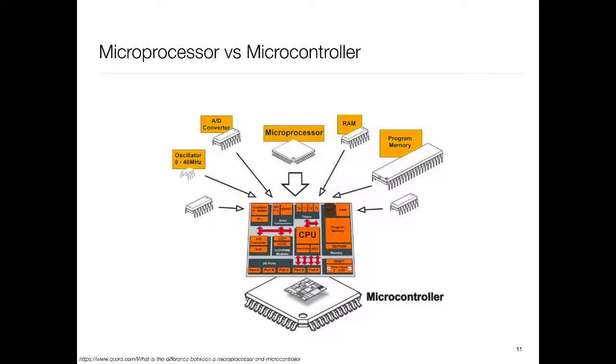Okay. So what happens with a microcontroller is that a lot of things which otherwise would be on the board are now on a single chip, but of course nowhere near the same size. So the amount of memory you would have is very little. In fact, most microcontrollers do not allow you to plug in external memory. If you look at a microprocessor, it would have an address data bus which goes out, and you can put memory-mapped things, memory and peripherals, onto that bus.